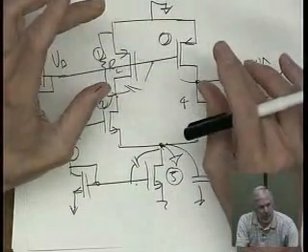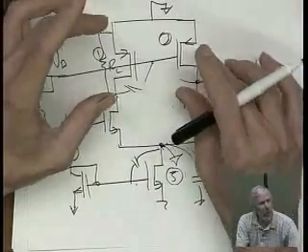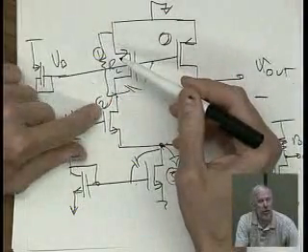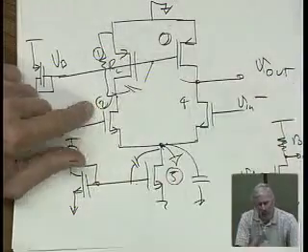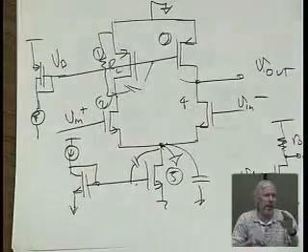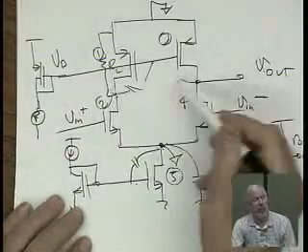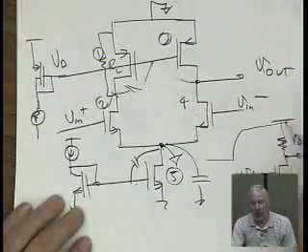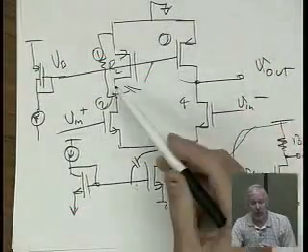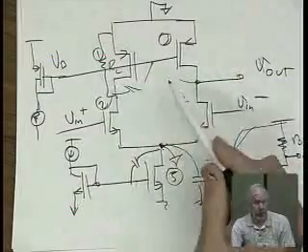Just to tell you what happens, the result will be, actually, this will create a zero. It creates a pole-zero pair, okay? You call these doublets. When you have this mismatch of two sides, you get a doublet. It's a pole-zero pair, which adds a little bit of weirdness to your whole design. Maybe we should do a homework problem that will do this for you.